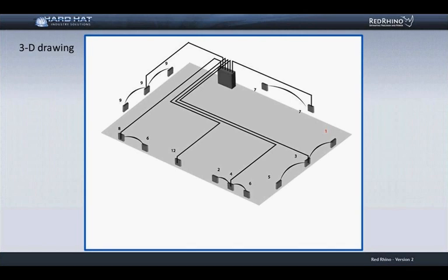When doing a conduit takeoff, you must include the length of the conduit risers. This was explained in previous sessions. Refer to them if you do not know what a conduit riser is. Here are the conduit risers, which are the conduit that runs out the top of the panel and outlets.